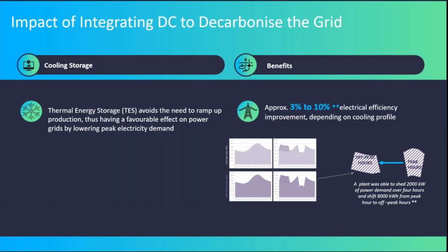And thermal energy storage coupled with district cooling is a big advantage, not only in terms of energy efficiency, but also security of supply. And when we think about the storage problem that we have when we introduce intermittent energy in our grids, we can understand the importance of storage today. We know that storage is expensive, but we often forget that one of the cheapest ways to store electricity is basically through thermal storage, in this case chilled water.